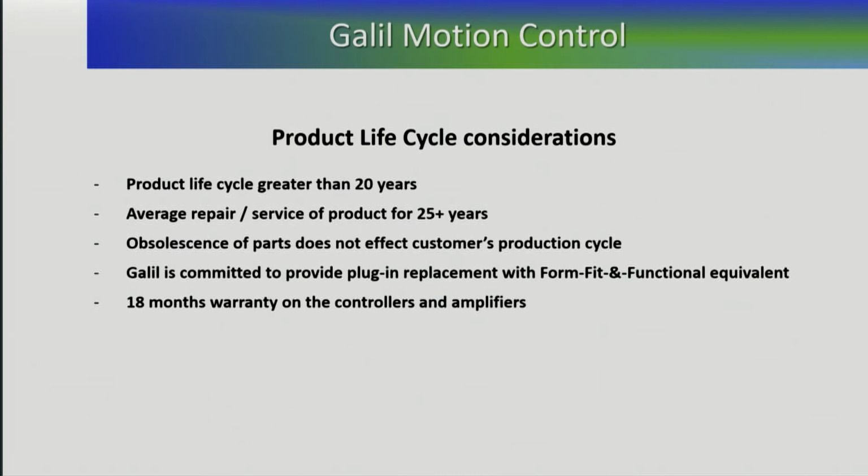unnecessary work. One of the things you have to keep in mind is how long the product is going to be available. Typically, when Galil offers products, we tend to provide product for a 20-year time frame. So we have an average cycle of 20 years. We have products that we actually introduced in 1988 and were available till 2013. So you had about 25 years of availability on the product. So that is one of the key important elements or parameters: you have to select a motion controller that will not force you to go back and redesign the motion control system in a few years time frame.